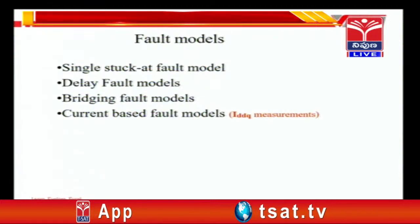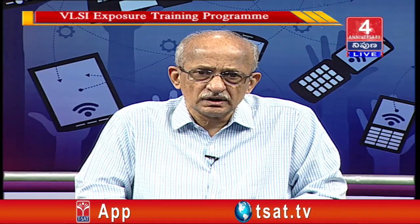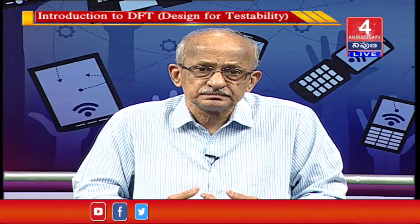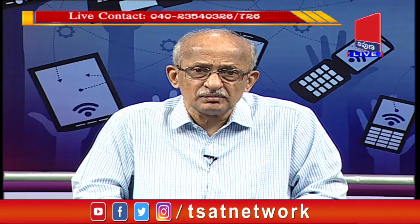As I mentioned earlier, whenever a chip experiences a little overetching of the tracks, two aluminum tracks, instead of being 1 micron or 0.5 microns wide, may be only 0.35 or 0.25 microns wide, in which case their resistance is going to be more. If that happens on a critical path, then the RC time constant increases and the chip may not work at the desired frequency.